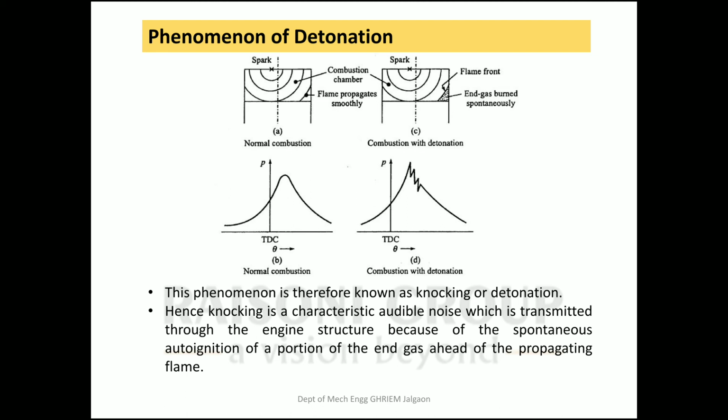The frequency of these pressure oscillations is the same as the fundamental frequency of the audible knocks. It depends on the velocity of the shock waves and their path between the consecutive reflections from the wall. Intensive detonation causes loud knocks with a higher frequency that arises in each cycle. The power of the engine drops and the black smoke appears intermittently in the exhaust gases.